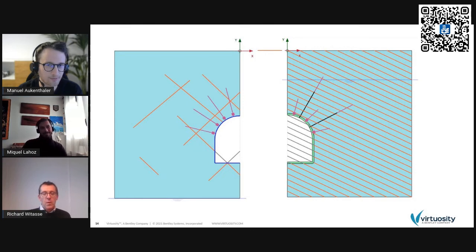By support, what we mean are the means used to support the excavation area, and reinforcement are the means to reinforce the soil, so improve the strength of the soil so that it remains as a unique mass and still has the possibility to develop stress arching. In PLAXIS, as you could see here, we talk about support.